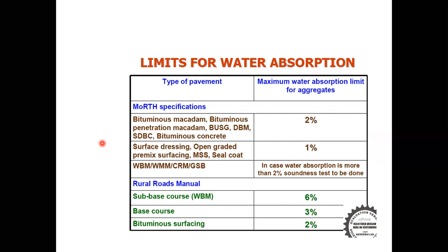The same W1, W2, W3, W4 that you do for soil, similarly here. And for specific gravity you are going for the wire basket method, okay, I will explain that. So if 2.4, 2.6, 2.7 comes, then it is a very good specific gravity for you. Even so many times you are going to assume the specific gravity of the aggregates as 2.6, 2.72, there is no unit, just 2.72.